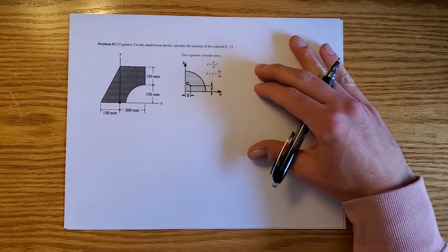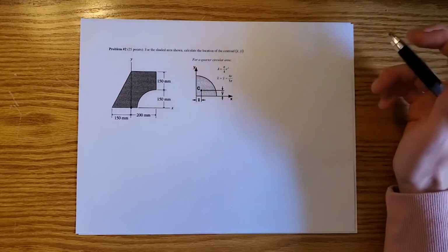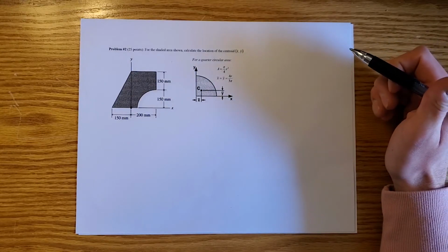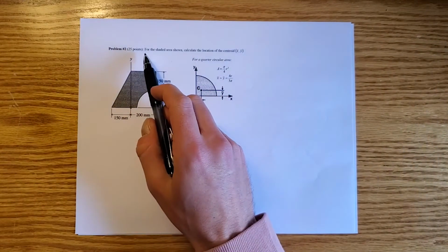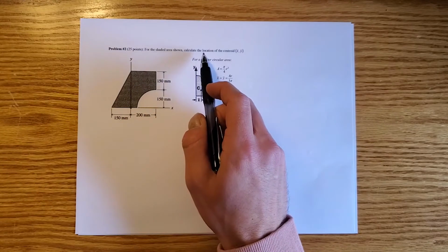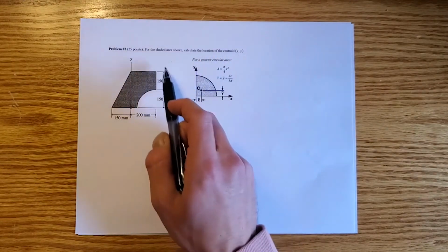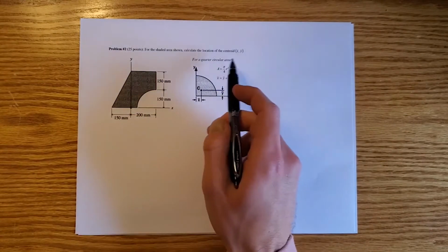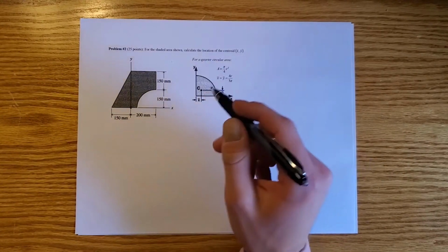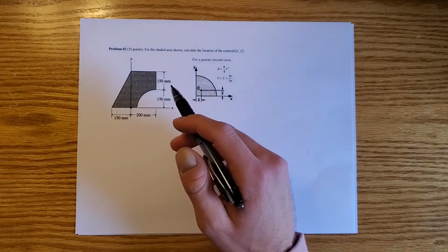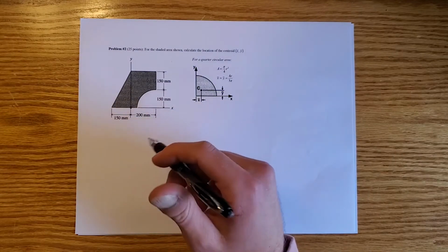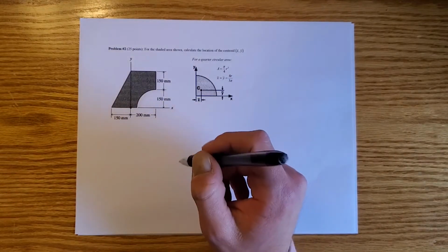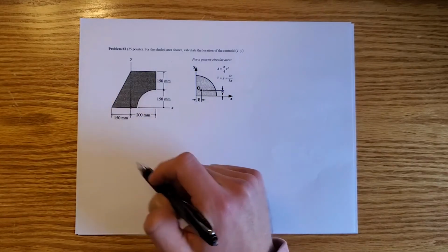All right, everyone. What I'm going to do now is go over problem number 2 from the old exam problems. Essentially, this problem initially asked to solve for the centroids x bar and y bar for the shape shown below. I'm going to solve for both of those, but then I'm going to add a second part to this problem, which is to solve for the moment of inertia about the centroidal y-axis. I'll go over how to do that in a little bit after I go over this first part.